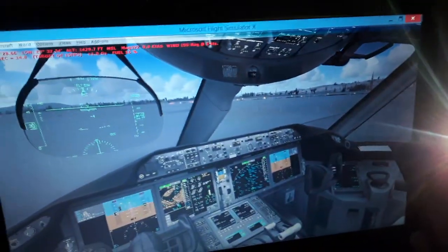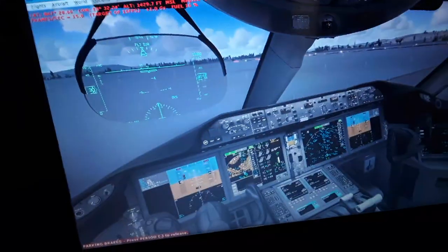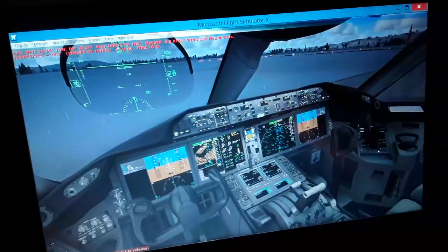From the GPS display, you can also see the navigation aids, the navaids, which are VOR stations, ADFs, and DMEs. Also the waypoints, which are horizontal and vertical navigation fixes with altitude and airspeed constraints. We're going to select some waypoints from the flight management computer that we're going to fly through, as we'll be flying using the flight management computer. We're going to make a flight plan, a flight path, or a route, connected with waypoints and a purple or magenta line. You're going to see it displayed in the navigation display and in the HSI also.